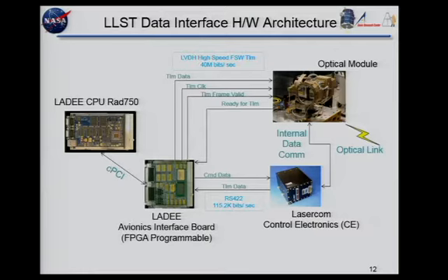And then probably the most complicated one was the lasercom payload. They actually had two interfaces. One interface was for the control electronics, and the control electronics had a 2 kilohertz control system running to keep the gimbal pointed so they could keep lock on the optical signal. But anyway, the interface was simple. It was just RS-422. And it turned out that this was a brand new development, so we worked early on on what the interface was going to be.